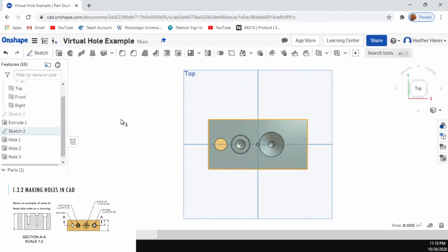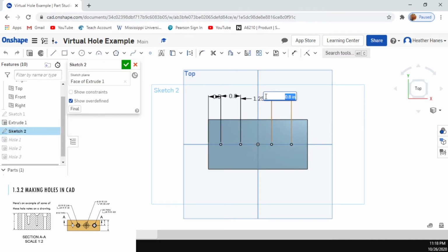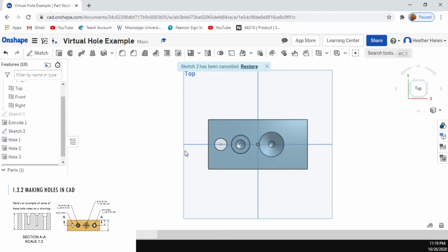Alright, I've got one more on this example that was online. I've got a 1/2 inch through counterbore with a 0.75 inch bore that goes down 5/8 of an inch. Alright, cool. How far apart are you guys? I might need to move this last hole slightly over as well. Do a full inch. Okay, that should do it. Oh, actually it might not. Well, we'll see. Worst case scenario, I've got to reorganize everything again.